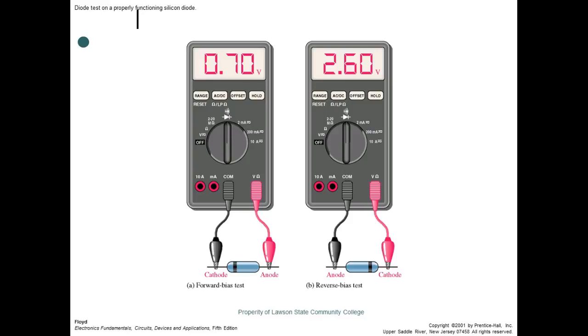So the first thing you need to do is just turn it on the diode scale and put your meter leads up in the air. Don't let them touch anything. And whatever it shows you, that's what it gives you when it sees an open. Y'all understand that? So if it says overload, that means when I reverse bias a diode, it should come up and give me OL.